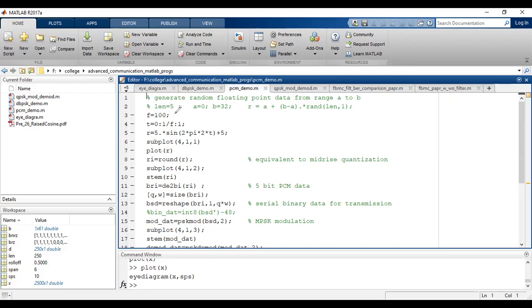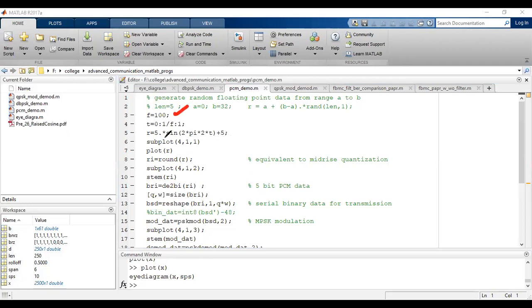Okay, see here, a sampling frequency of 100 has been taken, and a signal with amplitude of 5 volts, plus 5 to minus 5, has been taken. You can see a bias has been added because I wanted completely positive values. In your situation you can remove this and get negative values also, but in this particular program, I have taken only positive values. You are free to use any kind of program. So this one is completely DC.